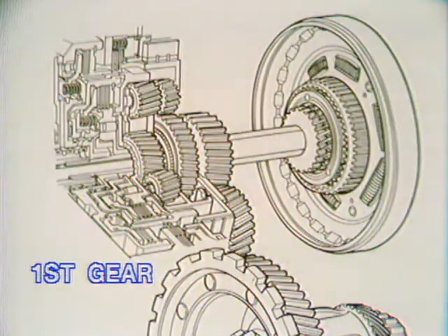Next on the chart is first gear, freewheeling. This, remember, is the first gear operation in D range or 2 range. The low and intermediate band is applied, and the one-way clutch locks up in the driving condition. Here is how first gear looks graphically.